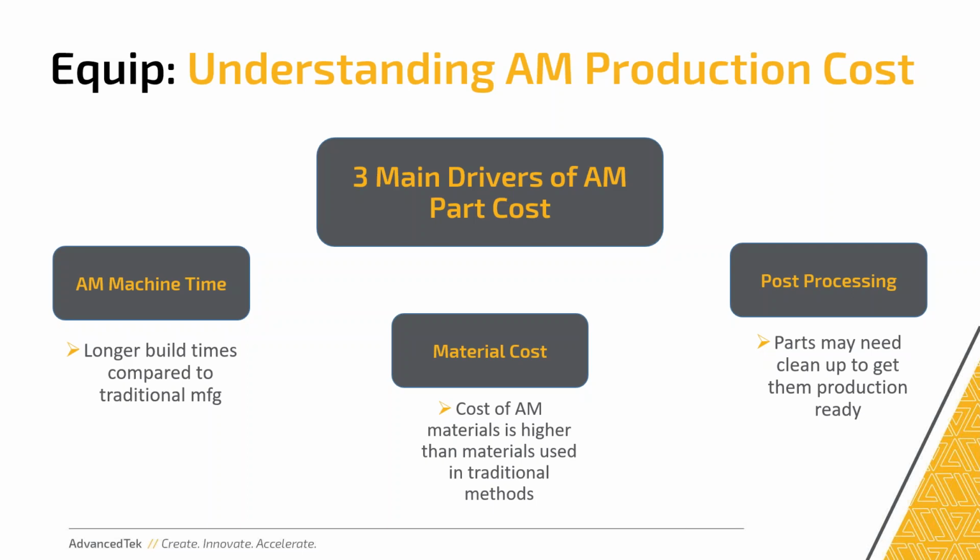And then a huge thing that people don't always think about is that post-processing aspect, whether that's removing your support or doing a machining touch-up. Your parts may not be production ready right off the printer, and to get them from the printer into your product may take a significant amount of post-processing. So those are the three drivers. And we'll take a look at that later on how to reduce